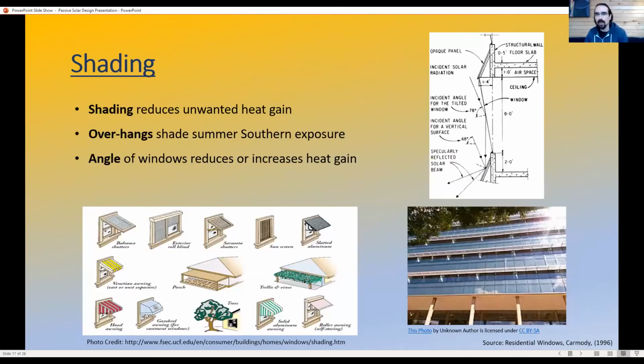Yes, here's my shading slide for the glazing. It's extremely important to shade your glazing on your south face to avoid unwanted solar heat gain during the summer, so you don't have an increased cooling load. And there are a number of different ways to do that.